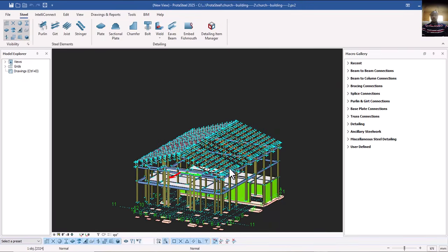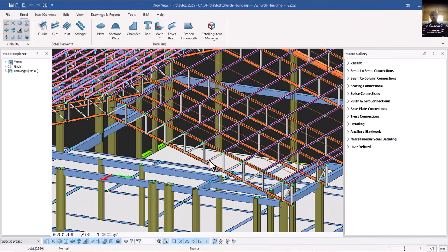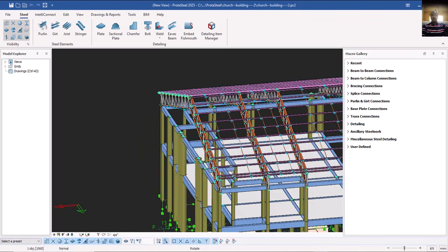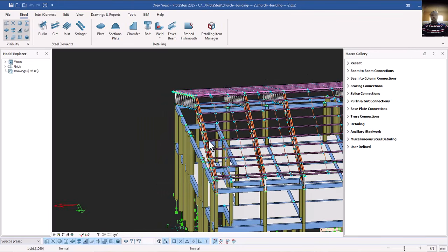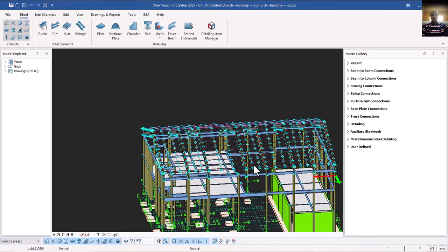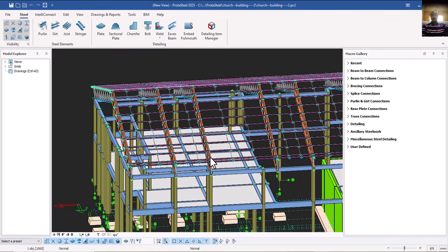It then means that if I can detail one of these, for example this first truss here, let's say this line, this particular one to that side, automatically I've detailed all of them. That's one thing I want you to know. Now, if for example this one is 90 by 90 by 12, I'm talking about this double angle iron 90 by 90 by 12, as I've already shown you the other time.